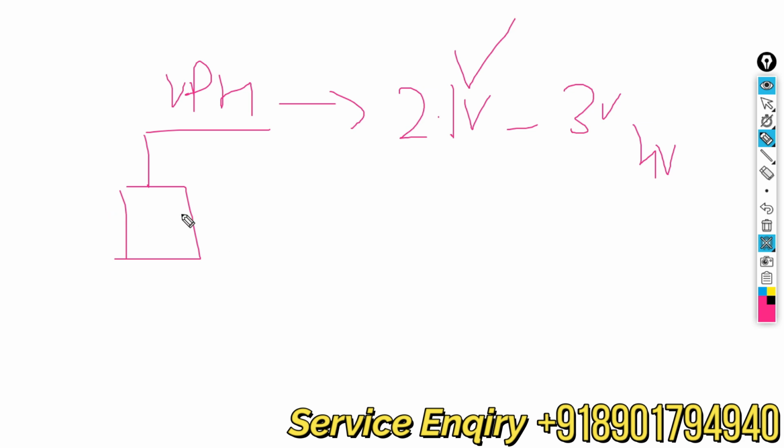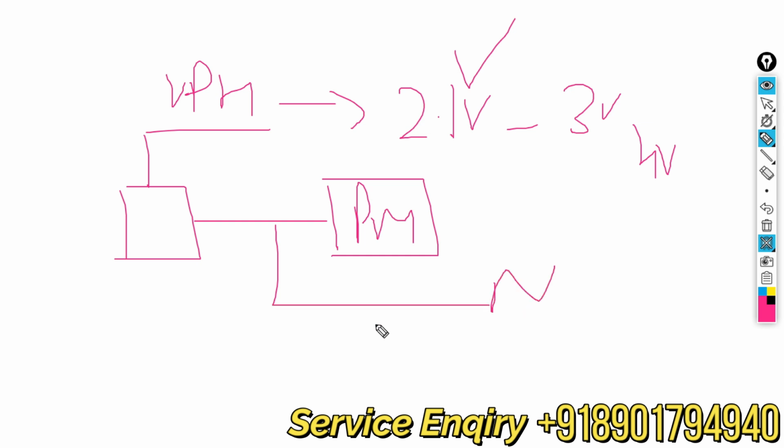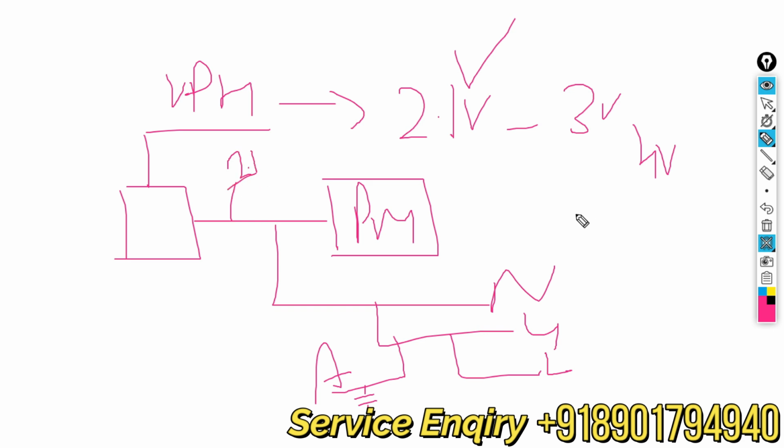It's okay, but let's say VPH is connected to the power IC, PM, and it's also connected to the other sections like network, graphic, LCD, audio, Wi-Fi, Bluetooth, many sections, right? Now let's suppose in the audio section a component called a capacitor has a leakage, not a proper short, only a leakage, or an IC leakage. You will see a similar situation, a similar current consumption, because this is also connected to VPH, right?